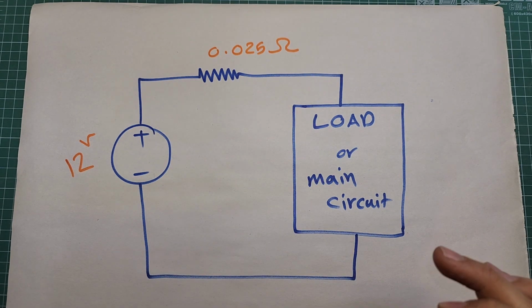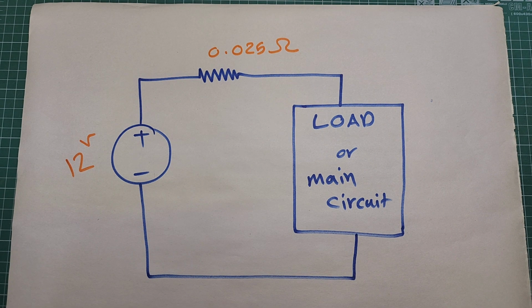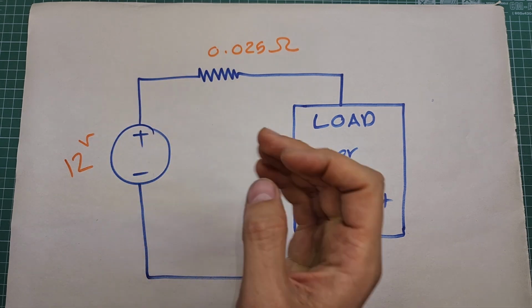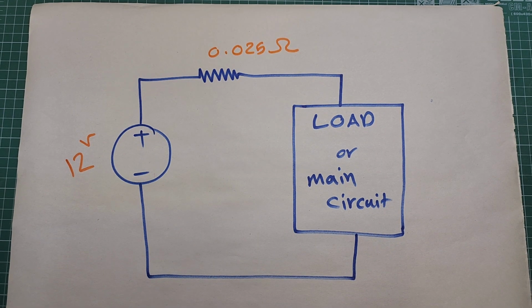But that's not the whole story, because when the voltage across this shunt resistor is very low, it also makes measuring the voltage across this shunt resistor very difficult, even impossible with regular tools like a microcontroller's ADC unit. Usually, to measure the voltage across a shunt resistor, which is very small, in the range of a few millivolts, for example, we have to amplify the voltage across this resistor before measuring it. And for this, in most cases, we have to use tools like Opamps.